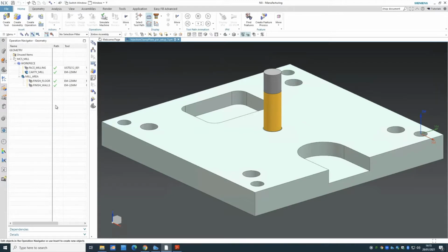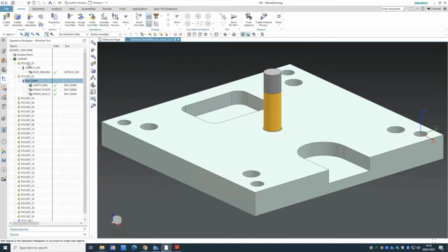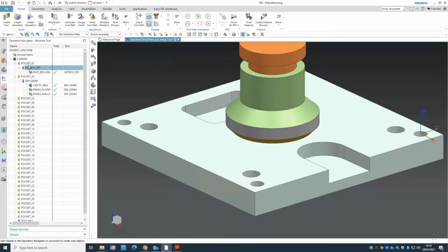geometry, that is really important. Once we set up the CAM machine, then for every operation, we need to make sure we already have the tool. We either retrieve it or we create it. And once we have it, we start doing the operation. If the sub geometry is required, we do the sub geometry first, create the tool, assign it to that sub geometry, and then create the operation. If it is not required, we already have the geometry, so we create the tool and then create the operation. So that's the sequence to follow.